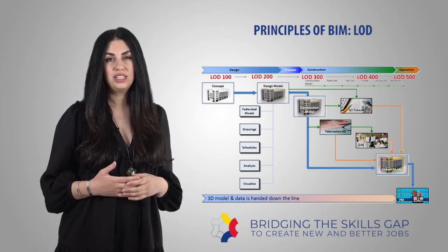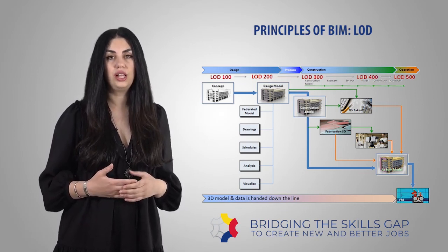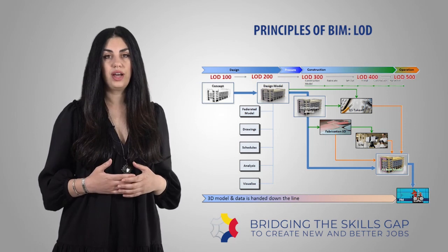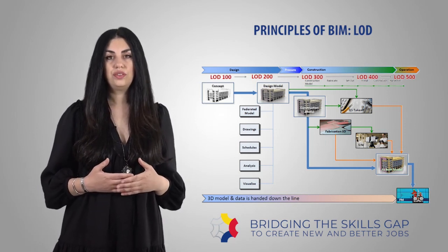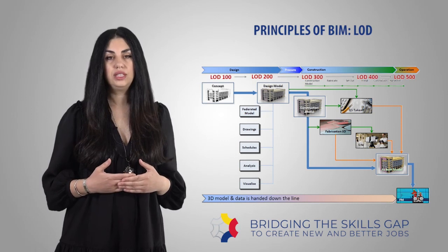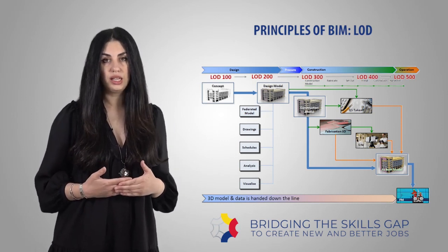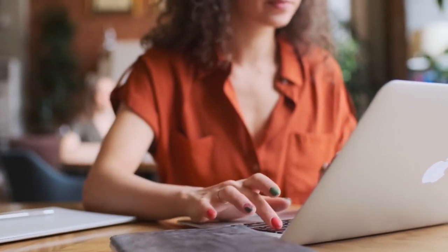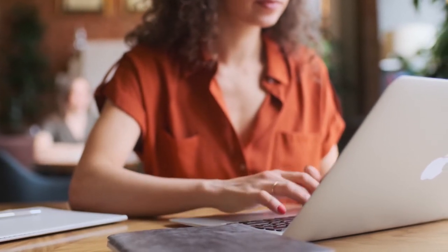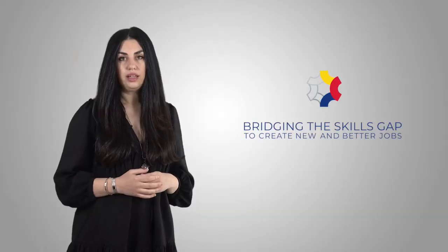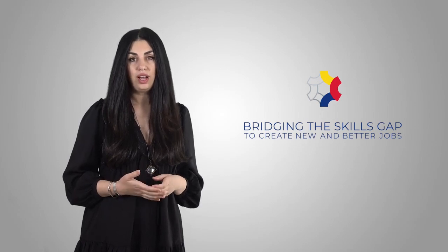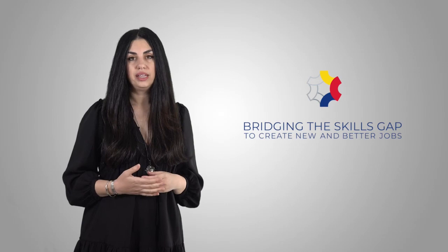Here's my opinion. It's not so much about using those official LODs. I mainly use them as a guide. What's really important is to define, according to BIM use, project phases, and delivery, the level of detail and information for each object, and as soon as possible in the process. You wouldn't need the same amount of information regarding the analysis, simulation, or visualization you want to run. This way, it will allow you to efficiently build your model so that it fits your budget. Otherwise, you could spend a lot of time making everything in detail.